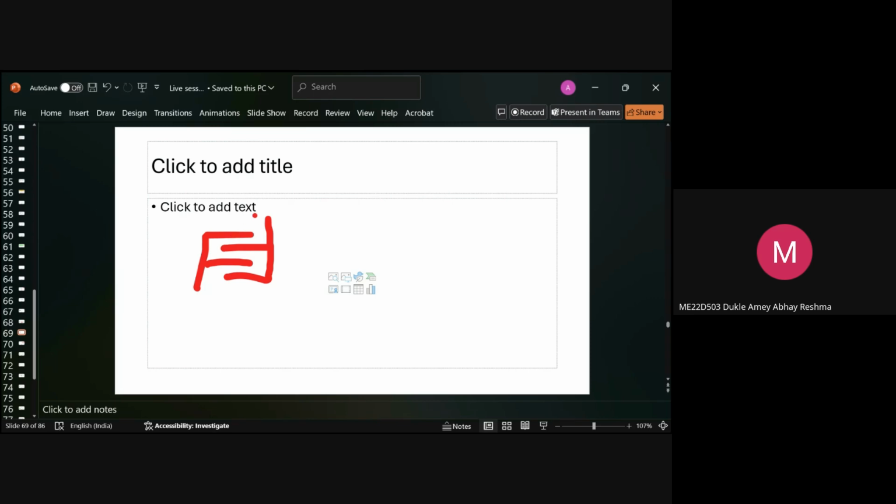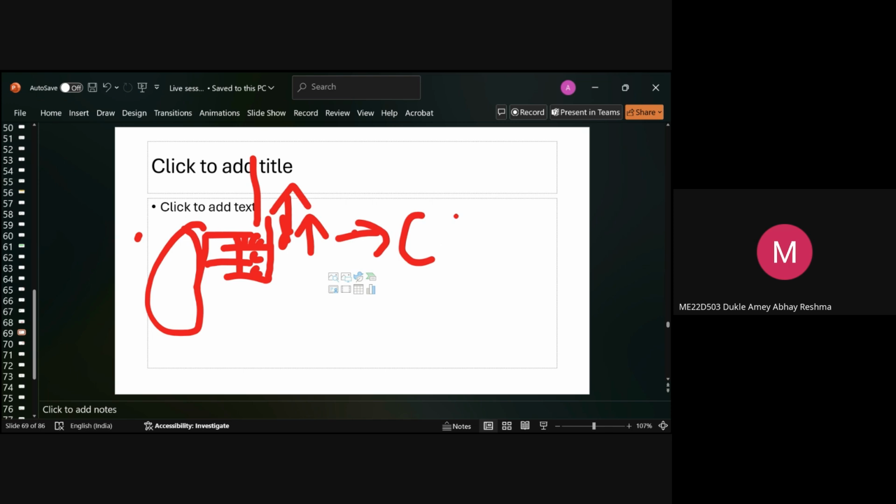So in an accelerometer, when the acceleration happens, this is a capacitor with C, this is a capacitor with C, this is a capacitor with C. When the car is moving, the acceleration is the change in velocity. So this will move straight, and this comb is fixed, and this comb is moving. So the distance between these two will change, and then the capacitance changes. When you get capacitance change, that is converted into acceleration.